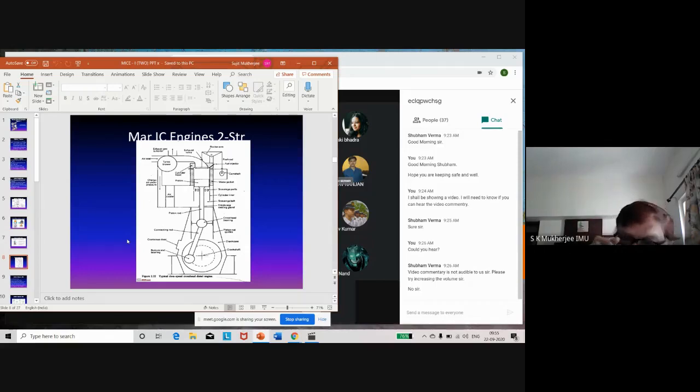So the designer of that bearing studies the load, the size, the speed, the temperature at which it works. And using these parameters, he decides on the viscosity of the oil that is to be used. Number 2 is the speed of the shaft. At a certain speed, that viscosity oil will be suitable because the speed enables the oil to be drawn to the underside of the shaft.